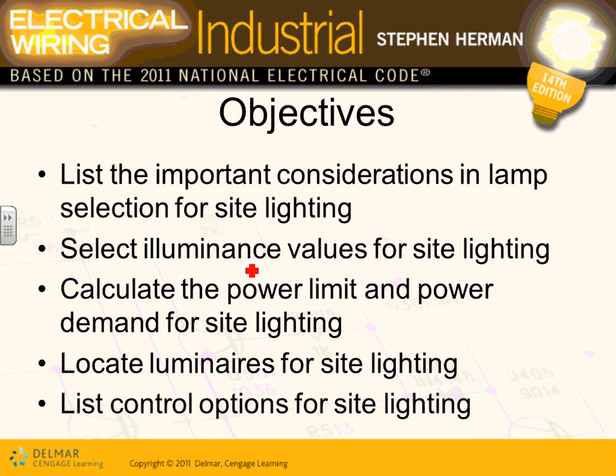So list the important considerations for lamps. When we talk about the lamp consideration, obviously our project, Adam, was LED, so we're really way ahead of this chapter. If you don't want to spend the time on LEDs, the lamp of choice is high intensity discharge. High pressure sodium or metal halide is the fixture of choice if you're outdoors in a parking lot and you don't want to use LED. So we talked about the considerations, guys. We talked a little bit about what factors to take into account when you select the lamp.